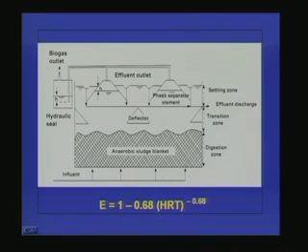So we are getting clear effluent from this portion, and all the microbial mass that has escaped through this portion will also come back to the digestion zone, and we will get clean biogas through this portion. So this system along with the deflector and the phase separator element is able to separate the gas, the liquid and the solids and retain a high microbial concentration in the system.